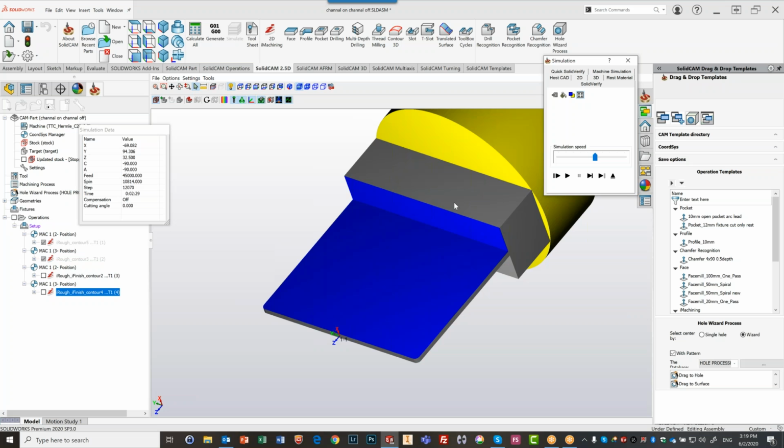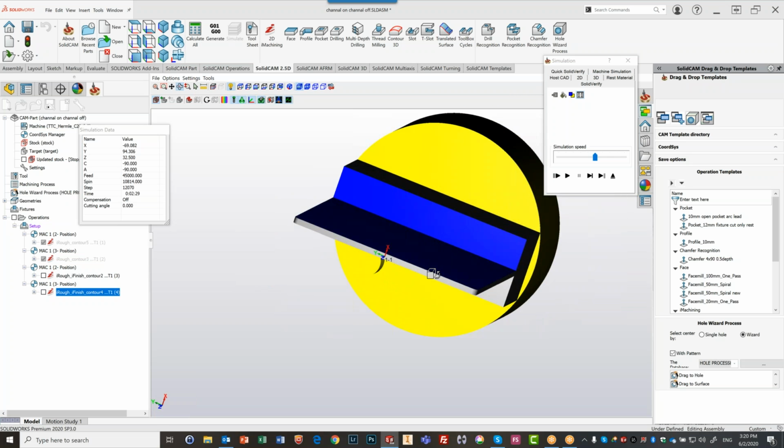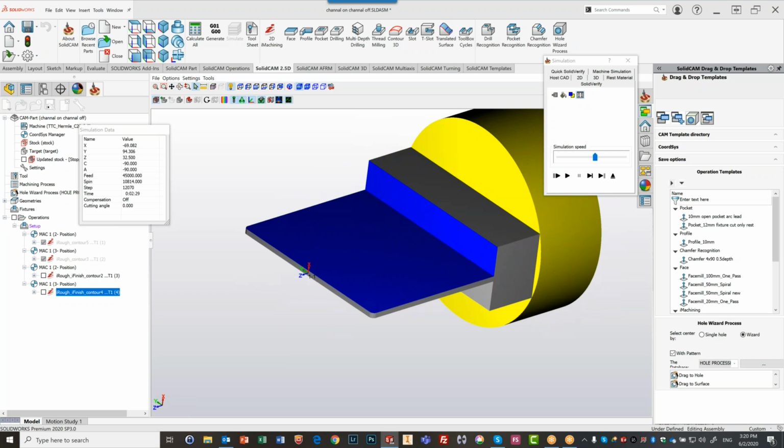Okay, so these are little tricks that's good to know because I can put a tool pass in it, it really looks nice. But I come to the machine, how do I work? What do I do when I have a situation like this, when I have too much vibration? Or for whatever, if I come to an area in any kind of machine that runs into this kind of a problem, thin walls, and it wants to do that moding, I can easily turn off the moding option and work this way.